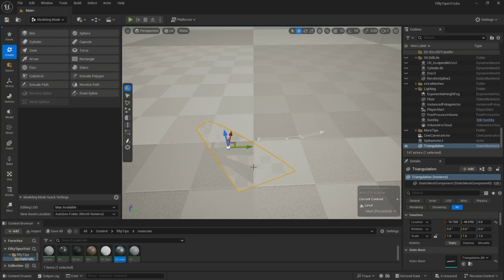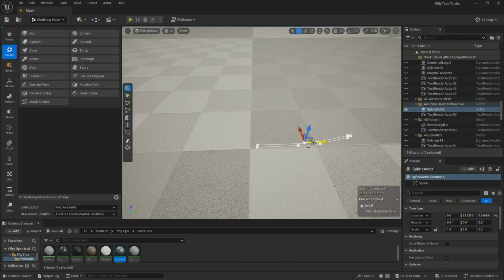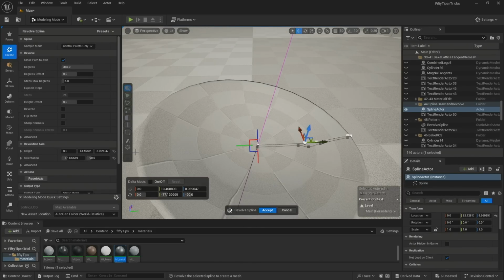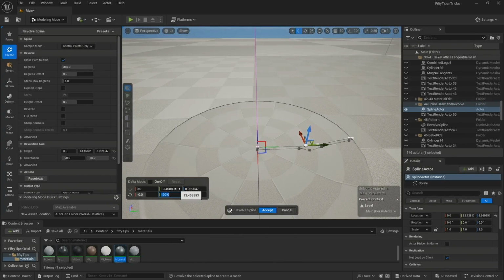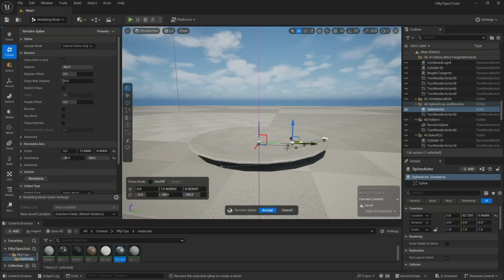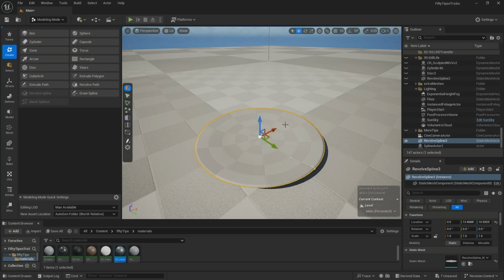That's all cool. If you wanted to do that, I'm actually going to take, again, I preemptively drew a nice little spline like this guy right here. And you can use that, and I'm going to say just revolve the spline so that if I wanted to do it, weird angle. Anyway, let's just change that to 90, not 900. So if you wanted to just do your traditional kind of revolving of splines, making of shapes, you can go ahead and do that kind of stuff. You can edit the spline if you wanted to. You can change the number of sections. Let's say instead of it being, we want to say explicit steps, let's just say 64, so it matches the 64 that I did for my mug. Kind of cool, easy way to do it. It's going to make my saucer plate for my food from later.